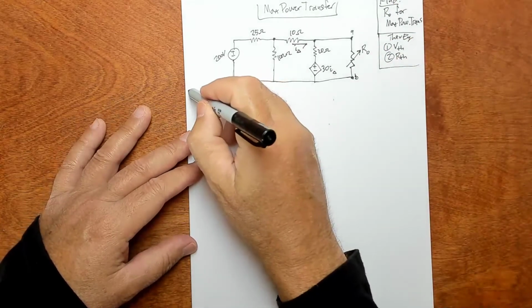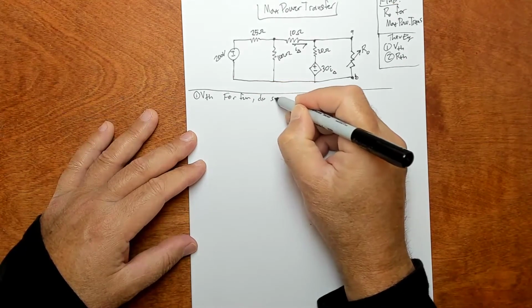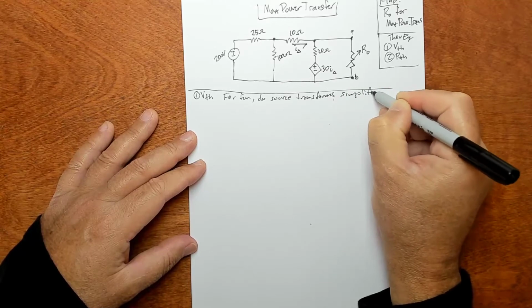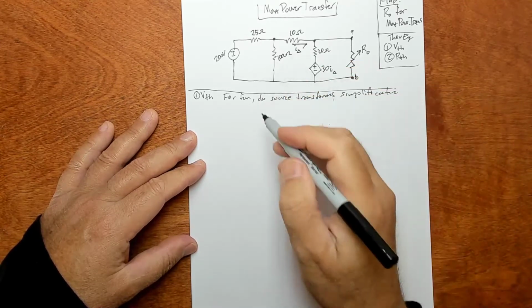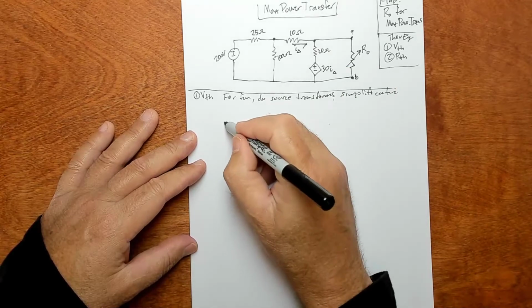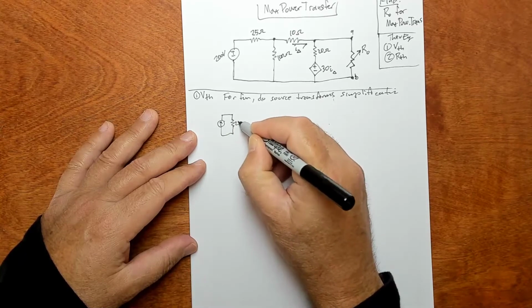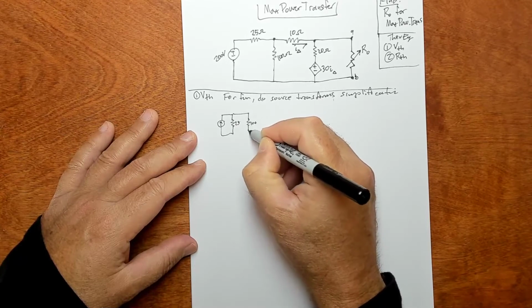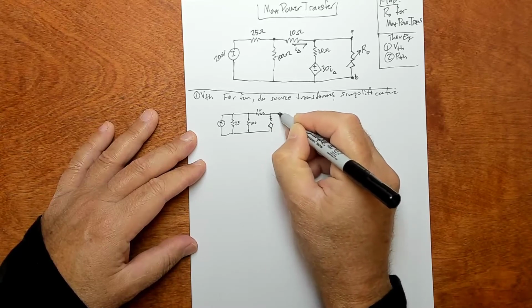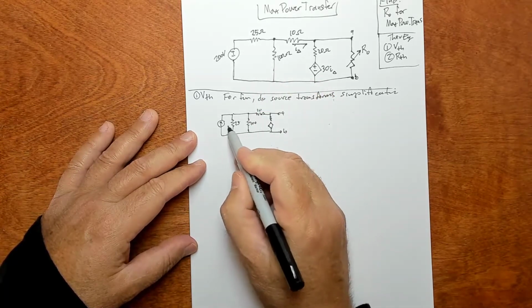But just to have some fun, and to show that there's a variety of other methods, let's do some source transforms to simplify this guy. In the interest of time, I'm going to do this a little bit quicker. So first you're going to get this guy. You're going to move the 25 ohm to over here. I'll draw it kind of tiny here, and then don't forget to remove the load. That is, do a source transform on these two guys and replace it with a current source and move the 25.